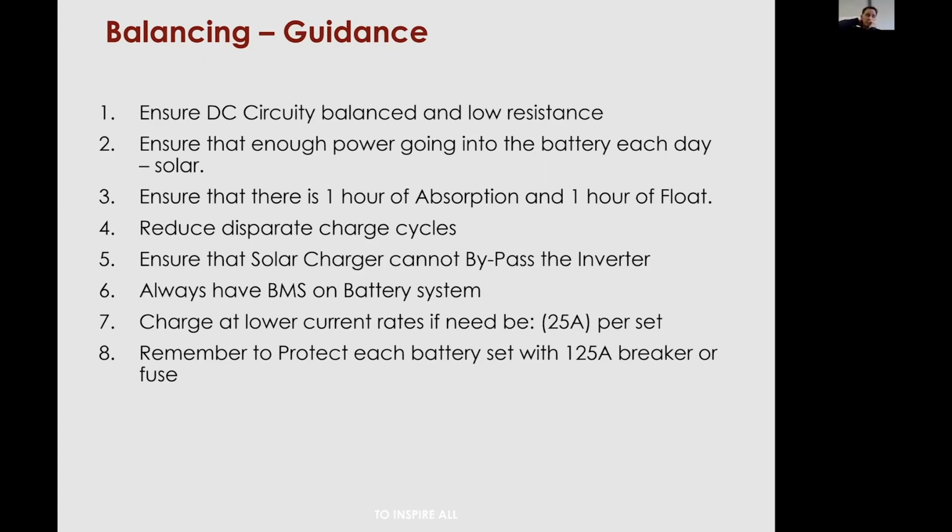Even though, if you don't have enough time in that absorption and float area, even though your BMV or your BMS reports 100% full, it may not actually be full. It's not synchronized correctly. So the only way to do that is to make sure you do have enough power and you are in the absorption and float stage for at least an hour every day.